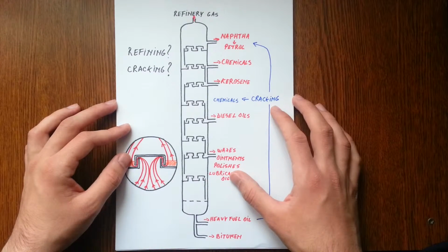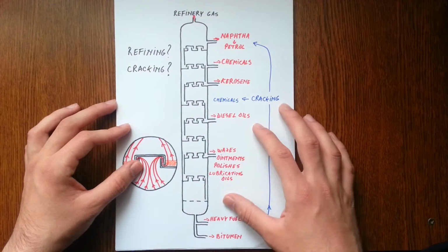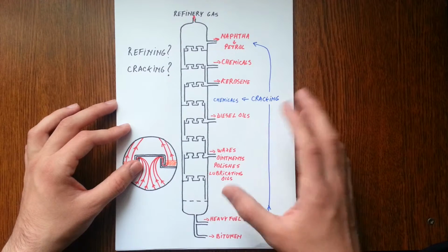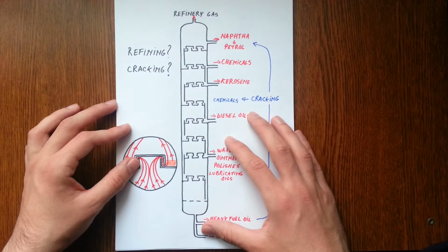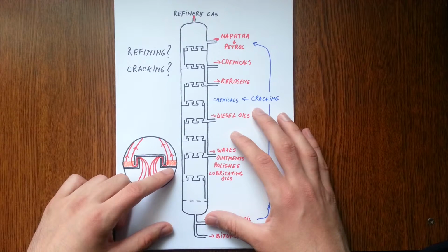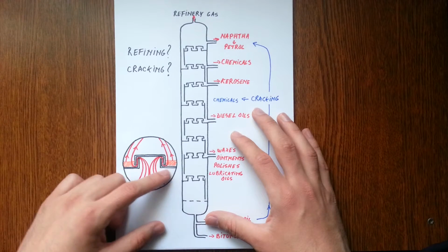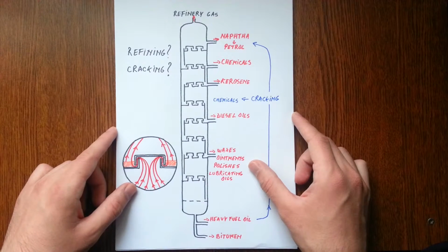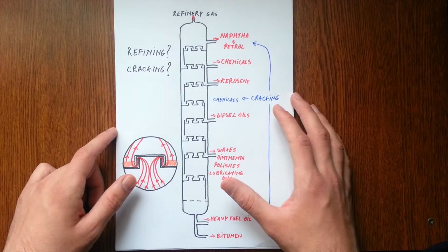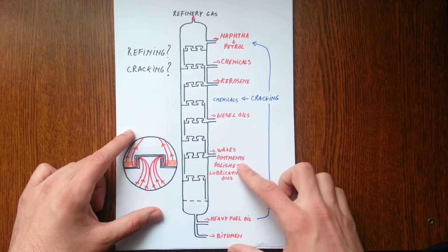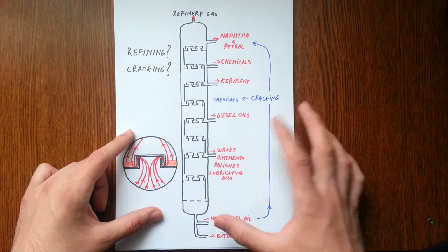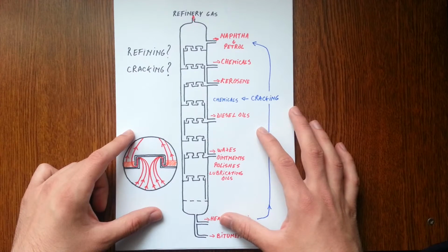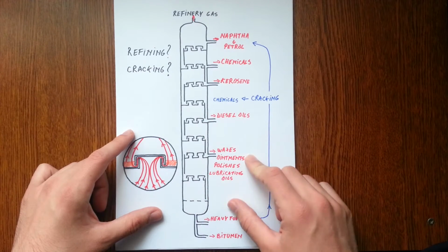The oil vapors rise up the column through devices such as bubble caps in the fractionating trays, which cause it to be thoroughly mixed with liquid already there. In this way, each constituent in the vapor meets a tray on which it condenses out. The result is a series of separated constituents called fractions, which can be drawn out of the column through some pipes.